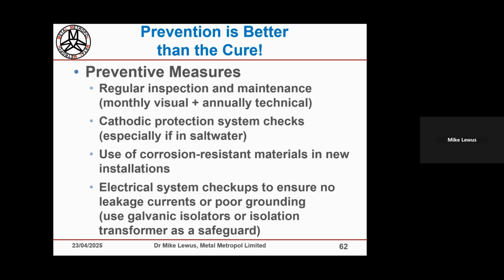Well, funny enough, there are. The important thing is the protection voltage, and usually for wooden boats, you want to be somewhere around minus 600, 650 millivolts. And there are actually specially manufactured zincs.